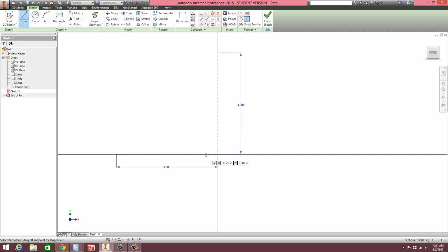So okay, once you have that, now we're just in the line tool. We're going to move over to the left a little bit. Like you see, my X is like negative 0.3, 0.4-ish. That's fine. Click, drag up a vertical line. Now just get it approximately 1 inch, but don't type in a value because we're not going to actually dimension the length of that. Click, drag it across. Now this one we do want 90 degrees, but we want it to be 0.4 across.